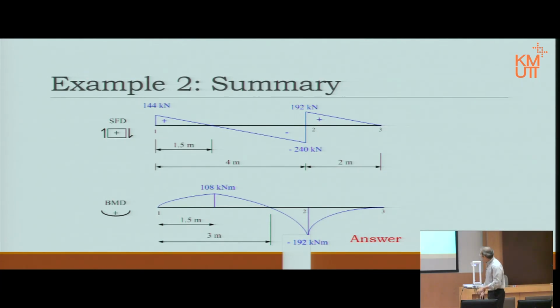So, that actually concludes the lecture for today. We learned first why we need the SFD, shear force diagram, and the BMD, bending moment diagram. Why do we need it, right? Then we learned how to draw it by generating equations, or we call them functions. We create the equation and draw the graph according to the function we have, right? And then with these two graphs, we can tell the maximum, the minimum values. We can tell where it cuts zero. We know everything, basically, about shear force and about bending moment within the material.